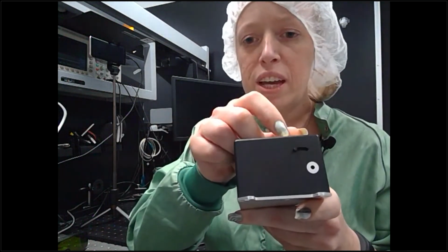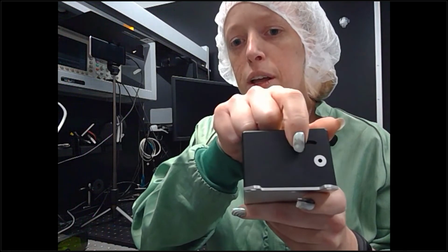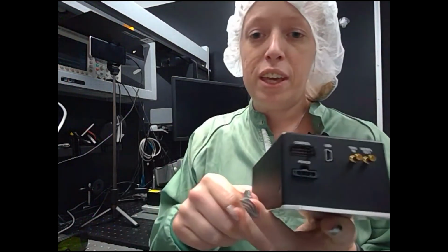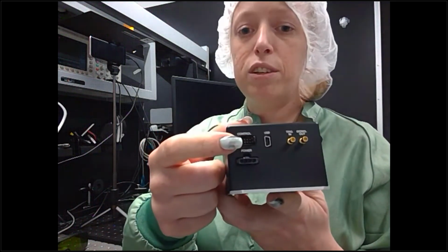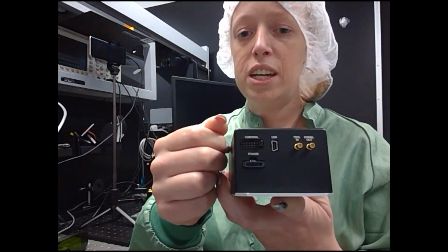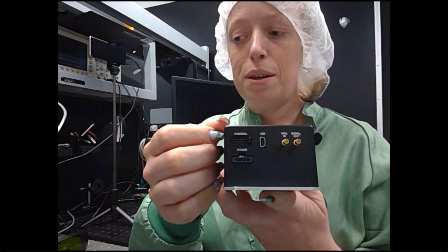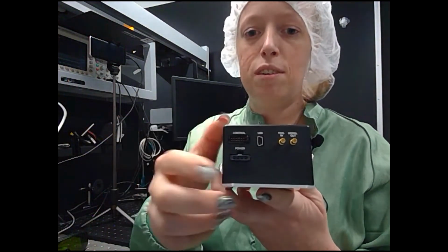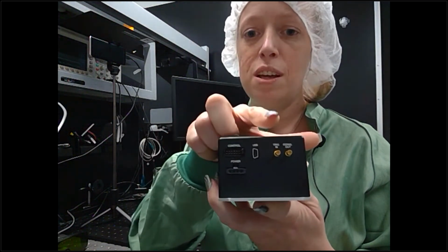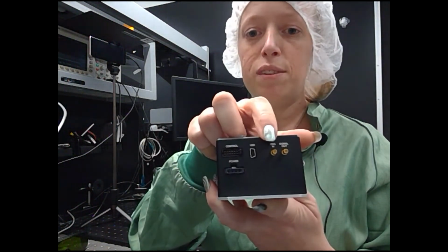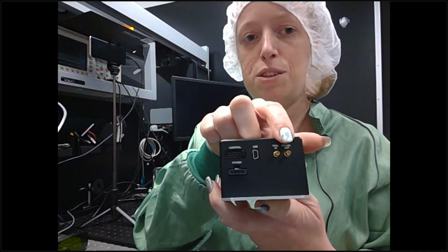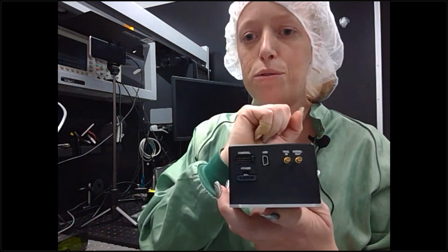We have, if I angle that so you see a little bit better, a shutter to open and close it. If we look at the back, we have a Molex connector, which you can use for a variety of purposes: the key box for CDRH, applying the trigger signal, RS-232 communication, and so on. We have the power supply connector, and USB for connection. You can apply your external trigger signal on the SMB connector, and we also have an SMB to monitor the signal coming out from the laser.